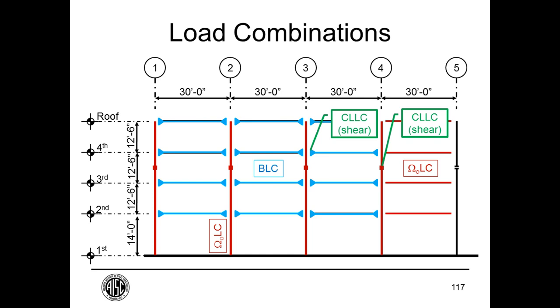Okay. And one final question, and it happens to also be on this slide. This will be our last question we get to. Do you design the base plate, anchor bolts, and connection and foundation with the amplified forces from the columns? Okay, so the requirement at the base does invoke the amplified seismic load.